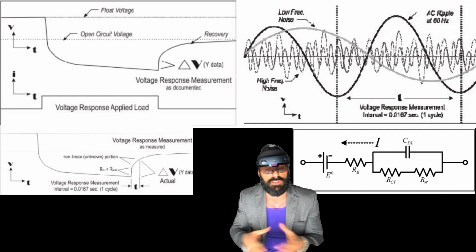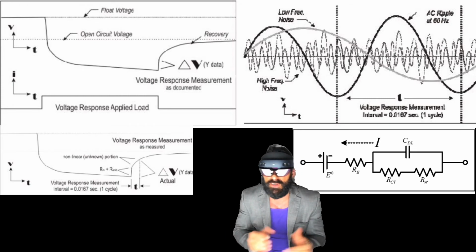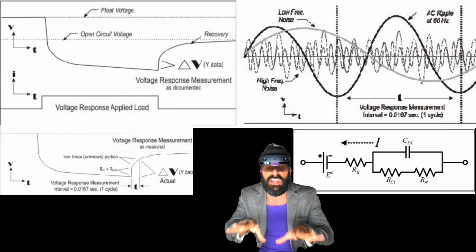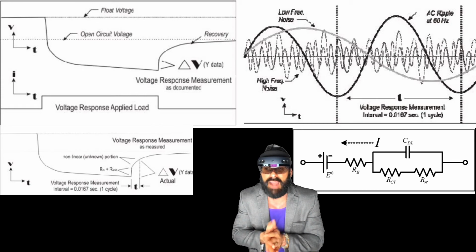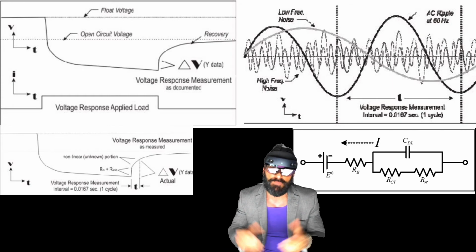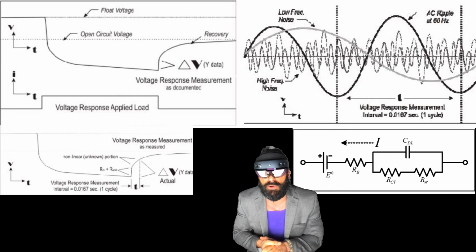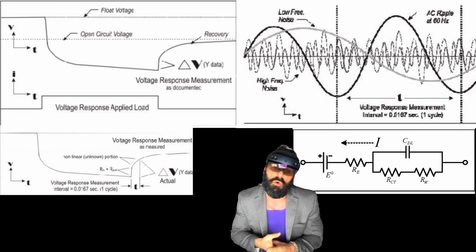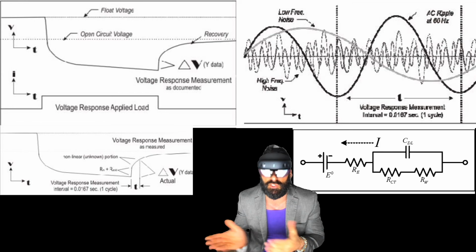I see signals, as I stated previously, up to 5 to 10 to 15 amps at various frequencies, cycling the batteries constantly, and you can literally feel it when you enter the battery room that has those components riding in the DC bus. It is anywhere between 5 and 12 degrees hotter. And as I've stated previously, most batteries are designed to operate at 25 degrees Celsius or 77 degrees Fahrenheit. You take the Celsius times 1.8 plus 32, you get your Fahrenheit.